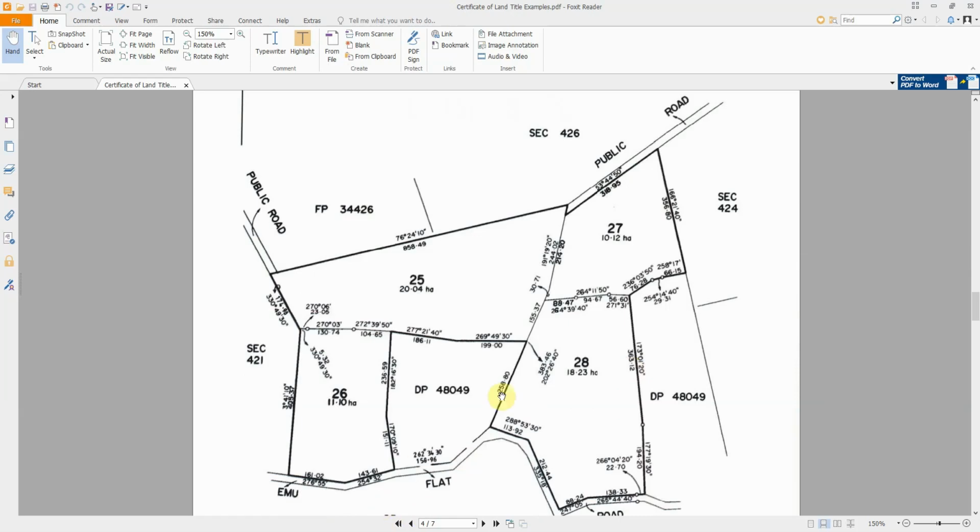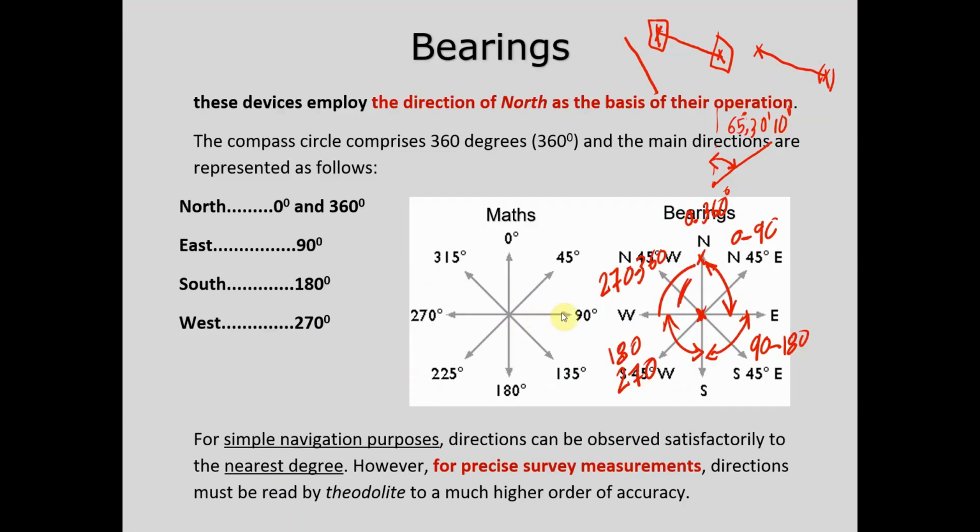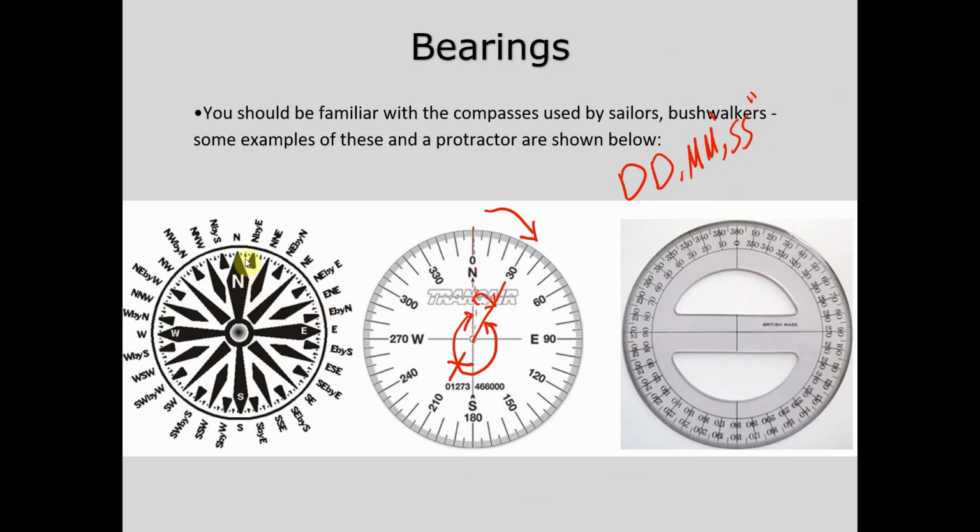Now, let's go back to our description here. How do we utilize this and understand it correctly? Number one, we agreed, the circle is obviously 360 degrees. Any circle is made of 360 degrees. That 360 degrees is divided into 4 quadrants, each one is 90 degrees. Our starting point for any line is the center. This is the center point here. That means any line, if I describe the length of that line and the angle with that north, I can accurately describe where that line is sitting.